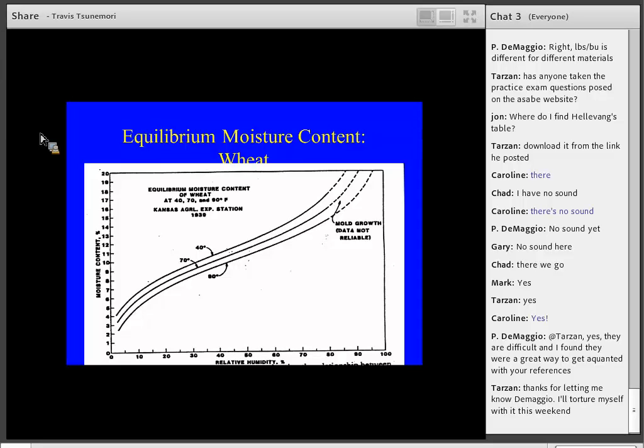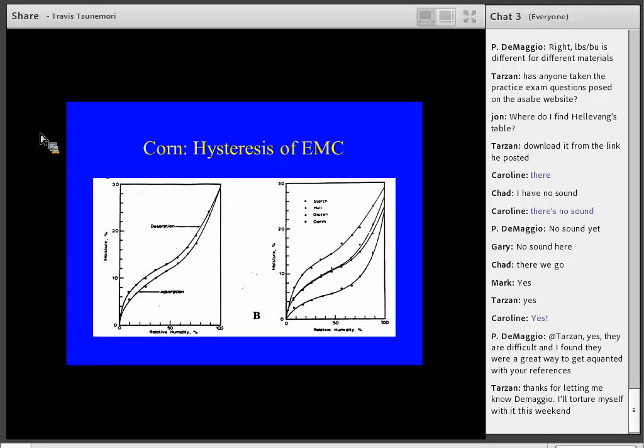So one thing you're thinking about is you really don't want to go too high in the relative humidity or you will have undesirable activity. You'll not be able to keep that wheat very well. So some of that may be in your natural environment. It may not be much you have or can do with it. A lot of times you can. And you may well do some work to try to reduce the relative humidity within your storage material.